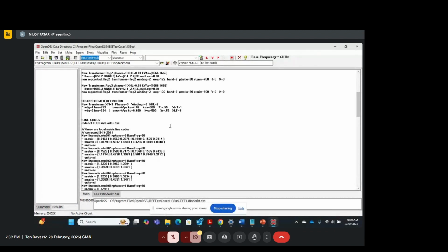Now from the secondary side of this transformer, you can connect like 10-15 houses, or all the customers get their own service. So that is where you have the secondary distribution feeder. So from 480 volt onwards, if you have another connection which connects like 10 houses or 15 houses, then that is a low voltage distribution feeder, or the secondary distribution feeder. And then 4.16 is on the primary.